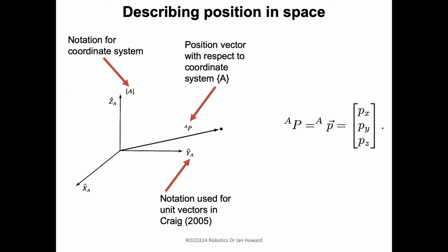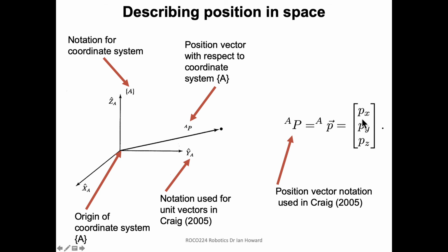This little a, because it's a three-dimensional representation, consists of three elements, X, Y, Z. We also note we have to specify where the origin of the frame is in order to have it well defined, especially if we need to relate this frame to another frame. The other thing we'll need to relate is, of course, the directions of the bases with other frames.